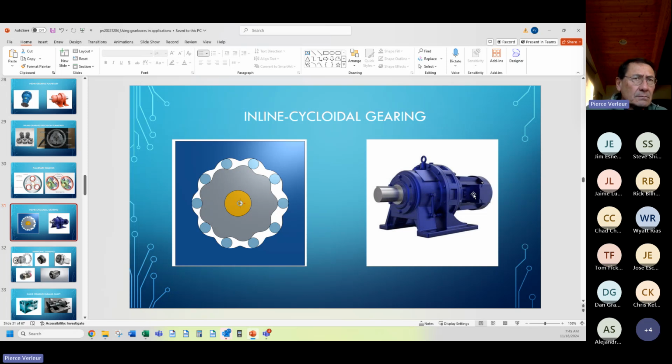Why is this important? A very good application of this would be robotics, where you move to a certain point and your end effector, whatever is at the end of the arm of the robot, needs to do something. Well, if that's a machining operation, or it's getting a force put on it, there's an external force from the load going to try to turn this shaft, and you don't want that shaft to turn. The stiffness of the system will determine how much it deflects under that external load.